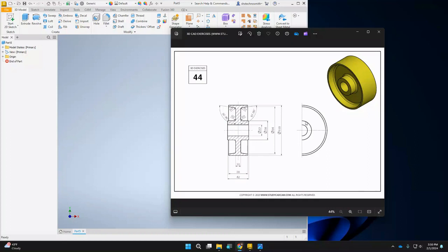And this one is going to go over Revolve. A lot of times parts are circular, but rather than making a bunch of circles and extruding and features and stuff, we can get into the middle of them and revolve. Revolve's kind of similar to mirror, where we're only going to do half of it. And this one's a great example because what you see here in the crosshatched region is this little shape. It's also mirrored, which is kind of cool too.